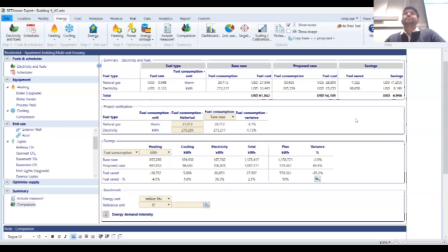Yes, go ahead. Basically, lighting energy is converted into heat in the space. Since we are converting to more efficient lighting, there's less heat that the lighting is contributing to the space. So that's why the HVAC system has to provide more heating to compensate for that. Correct. Does that make sense? Although you've saved electricity, your lighting is now not contributing to your heating as much, and that's why you see the negative therms.